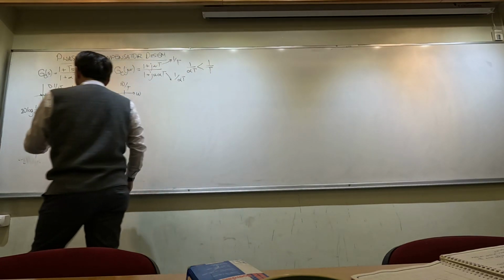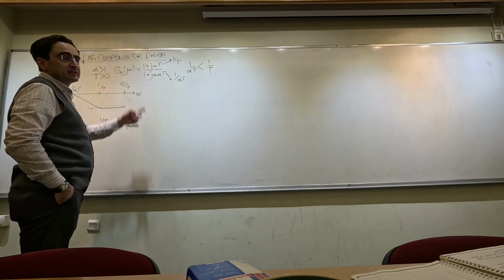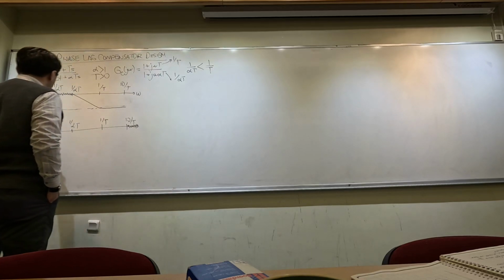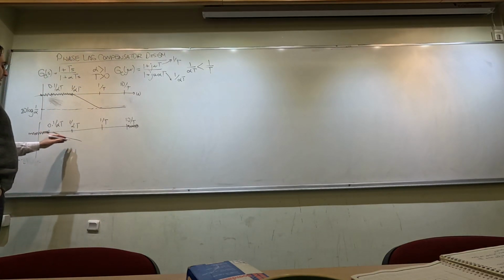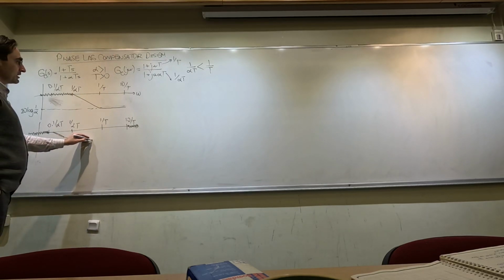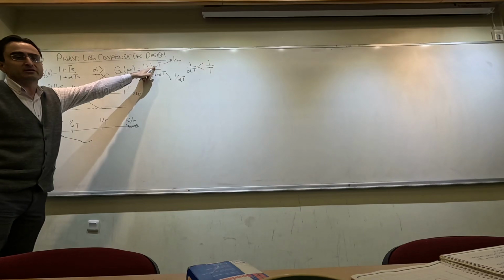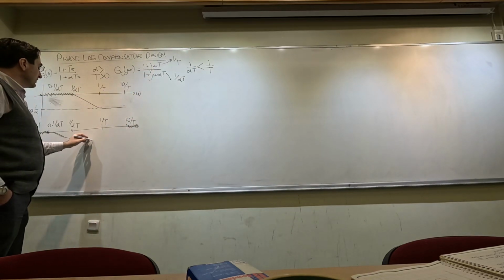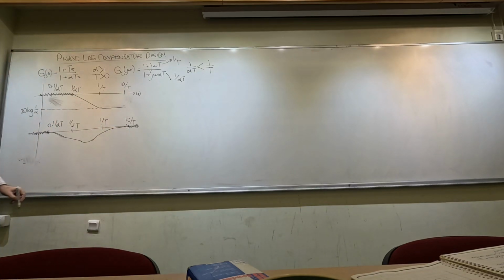Okay, and when the phase of the denominator increases, we get a negative decreasing phase. So this is going to start decreasing here, and at some point it's going to make a minimum, and then we are going to reach this. The phase of the numerator is going to start affecting the result, and it's going to be reducing the phase back to almost 0.